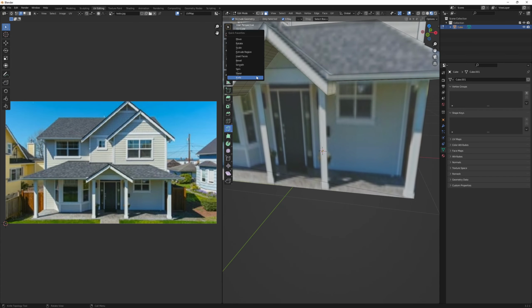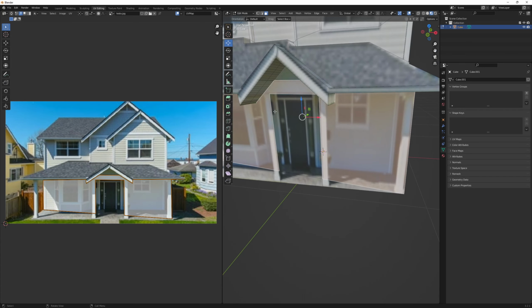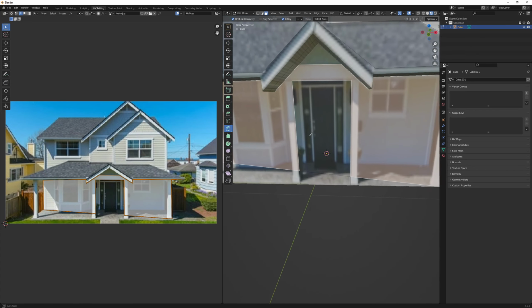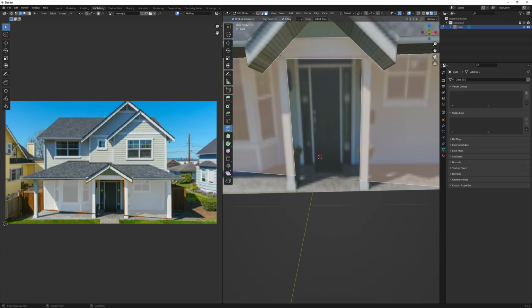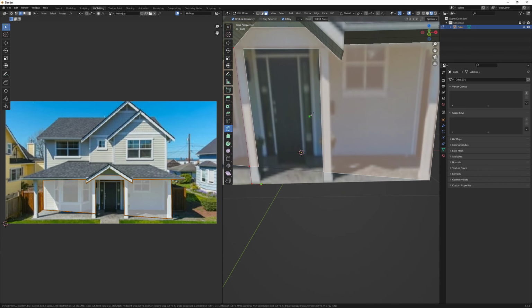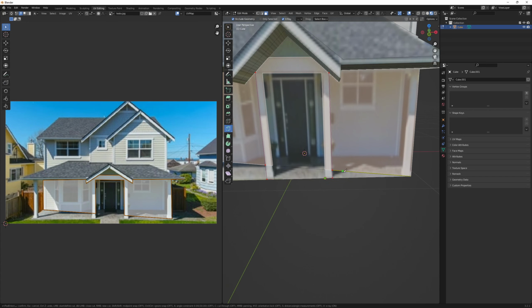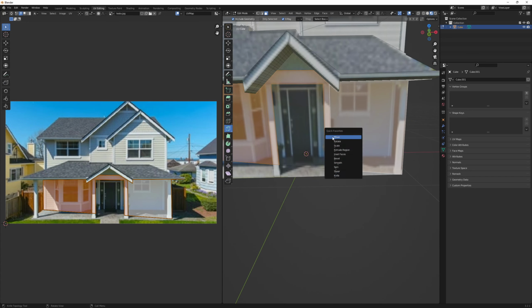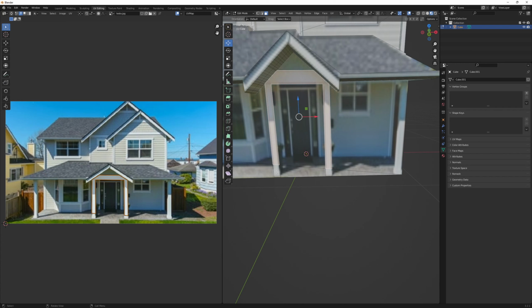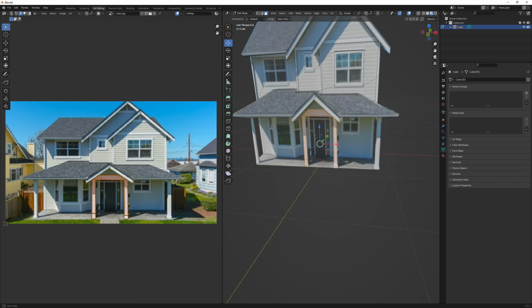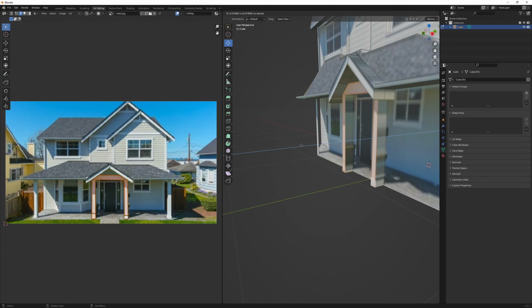And then to make it more 3D, we can make sure we've got the knife tool and go around the edges now. As straight as possible will help. So it's connected. We'll hold Control to make sure it doesn't snap. Across and press enter. And now we can go ahead and select our image, and then do E to move it out.